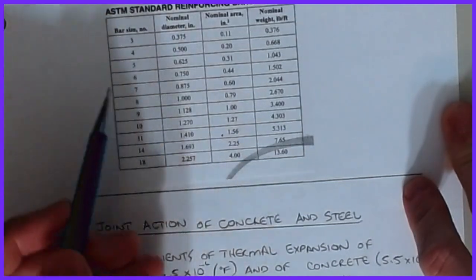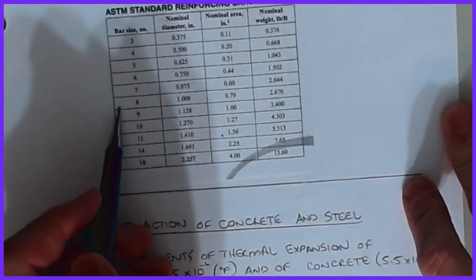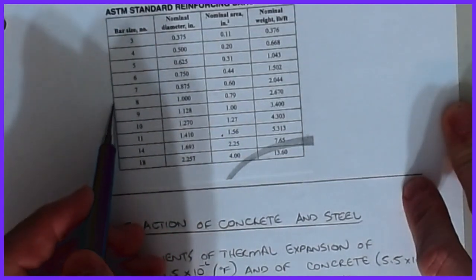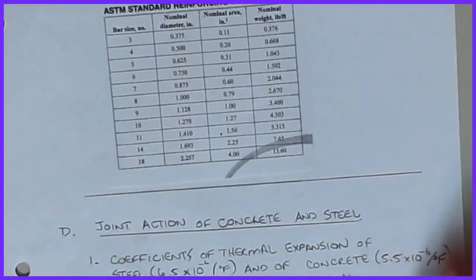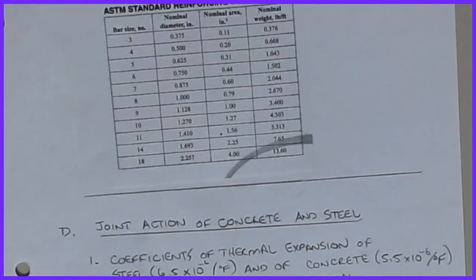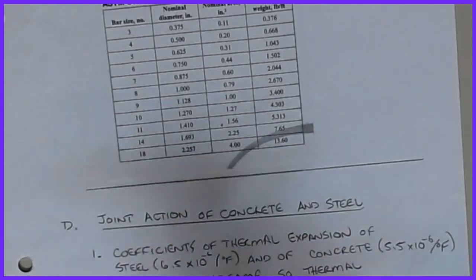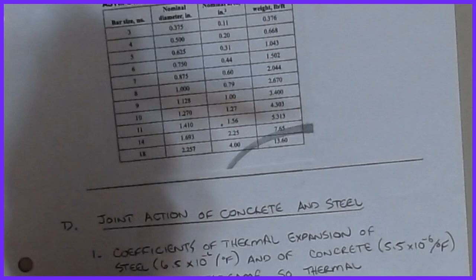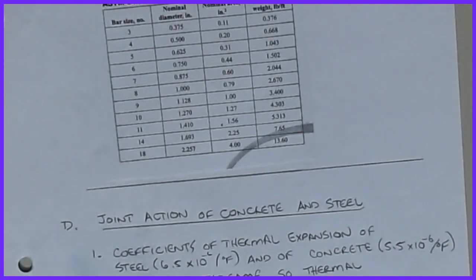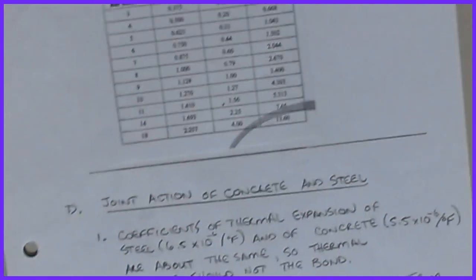Okay. Generally, when I do a flexural design, I like to try to end up in like the 6, 7, or 8 range. That just seems to work out the best as far as development and detailing, and avoiding factors like congestion and too many bars in a small location. It seems to work out very, very nicely. But there are reasons to go smaller, and there are also reasons to go larger that we'll also start to explore. Okay.